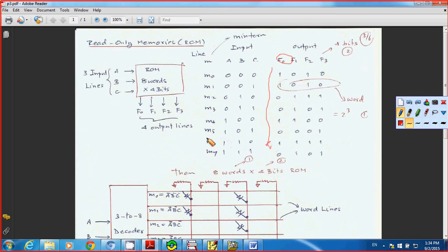Now we're going to take a look at the minterm, right? As you know, when you're talking about a minterm, you use the AND of the inputs, right? A has to be ANDed with B and ANDed with C. And for each term, you just OR them together. This means that you have to OR M1 to M4. But at this point, we are interested in F0, so you take a look at the minterm. What does minterm mean? A minterm is the term that gives your output to be 1. So I have right here, right here.